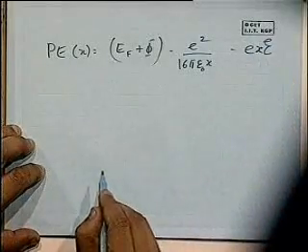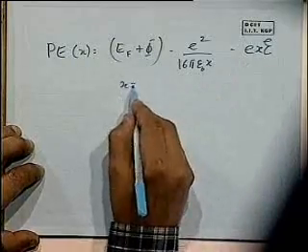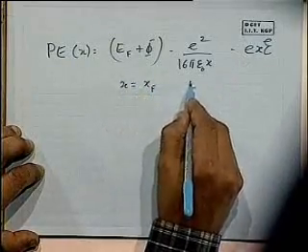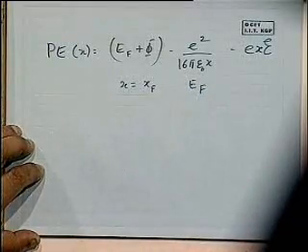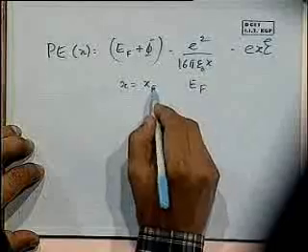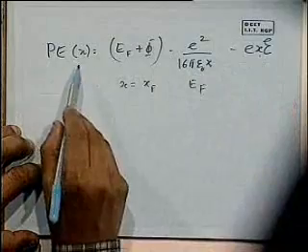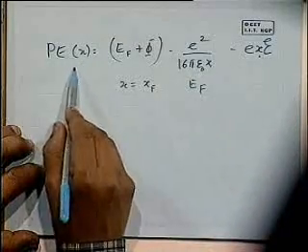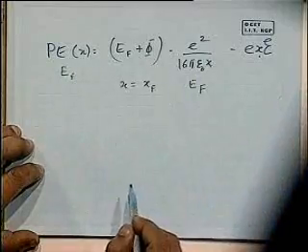This was the equation that we had. In this case, when x is equal to xf, the energy term is EF. That's how we define the xf, that at the Fermi level, what is the width of the barrier. So by making the substitution x is equal to xf, we can then calculate, and here we have EF is equal to this term, right?